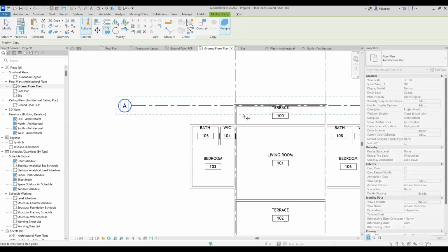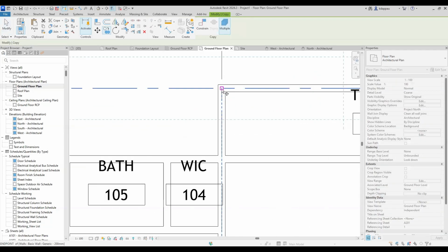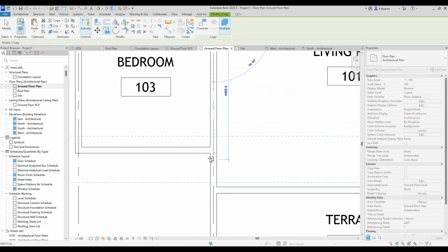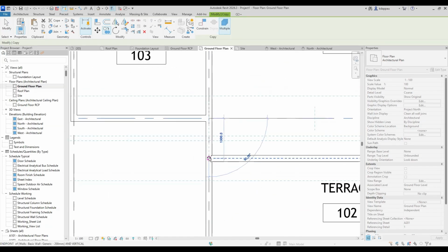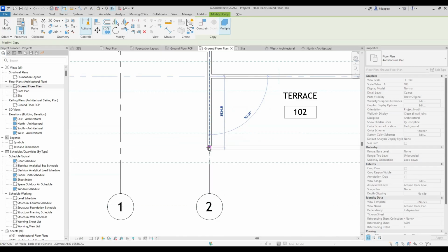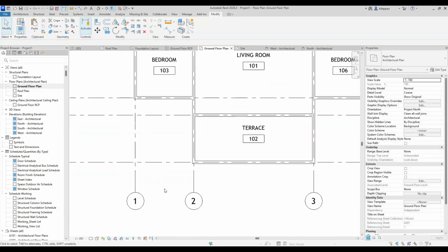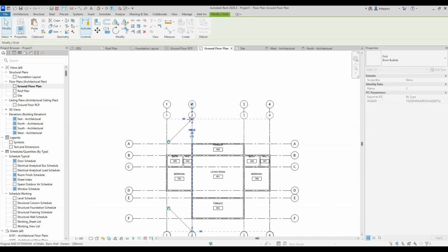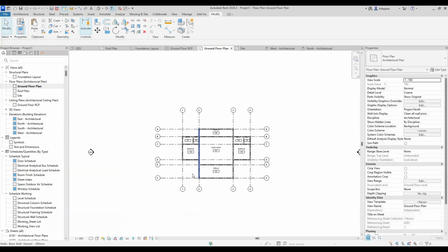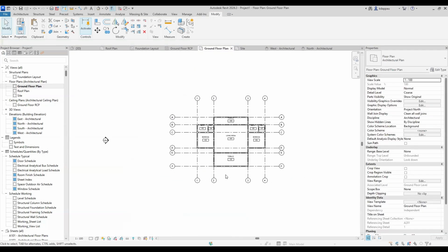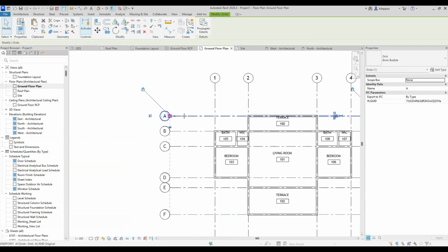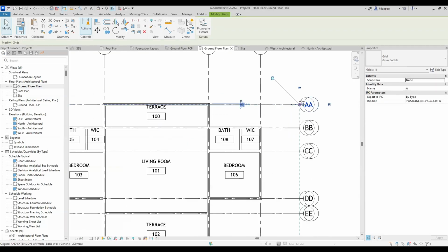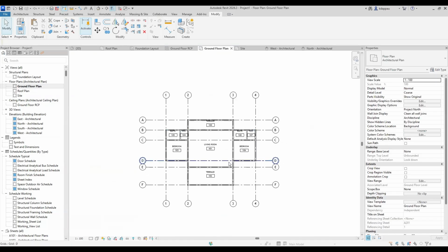Then when I'm done, I'll copy it. CO for copy. I'll copy from here to there, to here, to here, to here, and then to there. So if I see, I now have all my grids drawn. So I'll adjust this grid down a bit. They all move together. I'll adjust this one to the right a bit. I'm going to show you how you can make it uniformly drawn, but for now, just use eyeballing to do that. So I have my grid set.